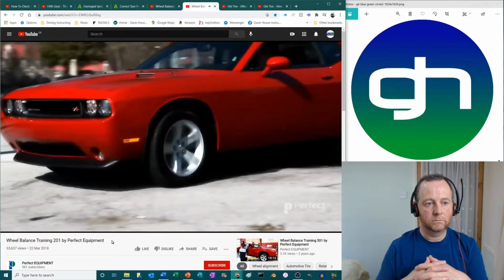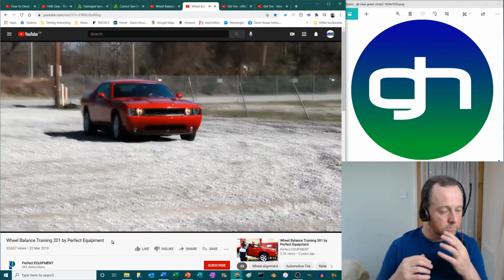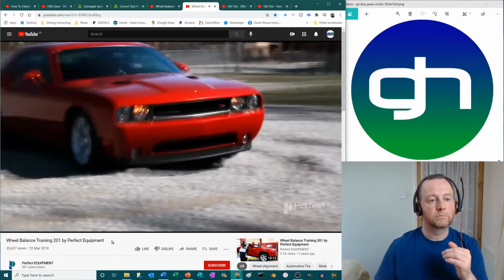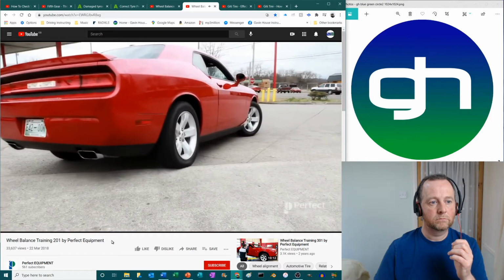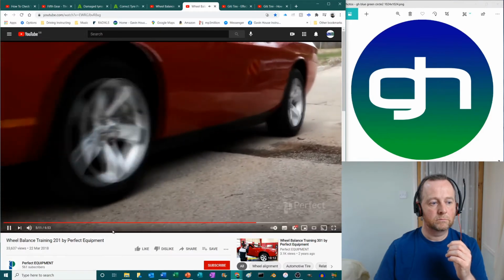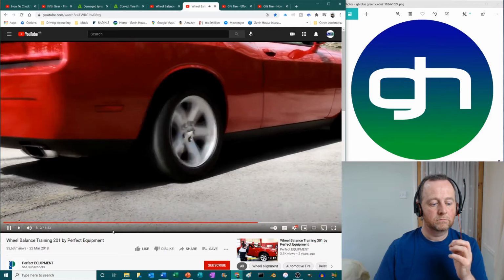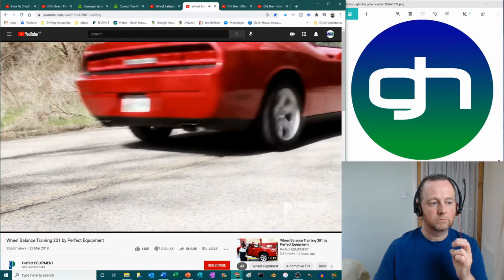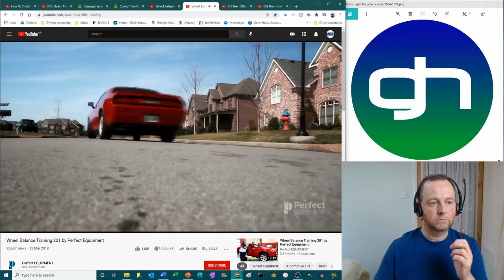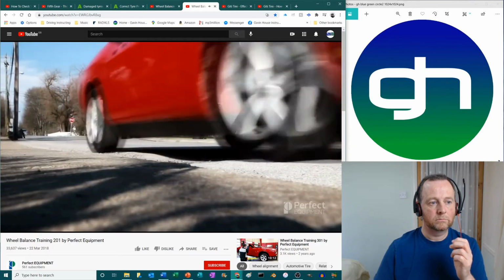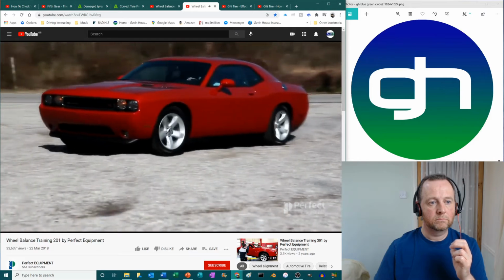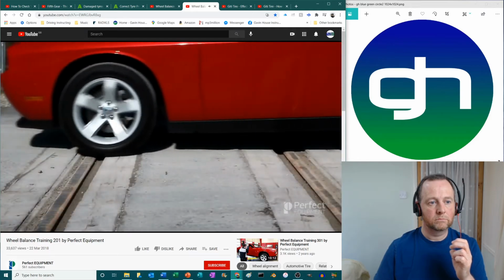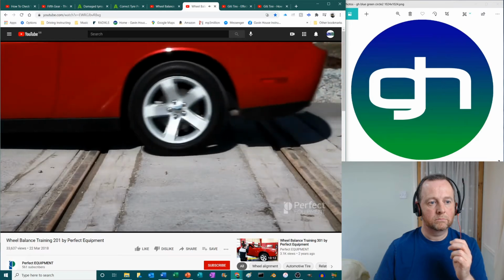Another main factor is driving conditions. When driving fast on uneven terrain, weights that are already on your wheels may fall off or slip, causing an imbalance. Running over the curb or hitting a deep pothole can also cause a wheel imbalance. Starting too quickly from a standstill or sporadic accelerations can even cause a tire to turn on the rim, changing its position. All of these conditions can lead to an unbalanced vehicle that experiences wheel shimmy and wheel tramp while on the road.